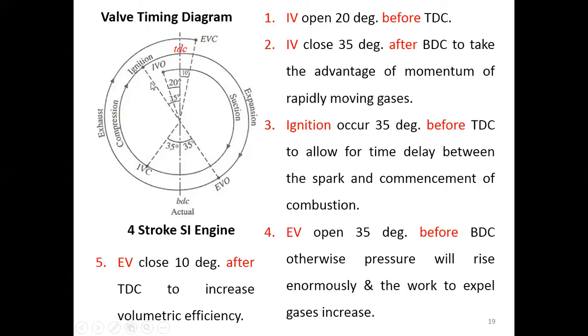Okay. Start from the inlet valve here. The inlet valve opens here. From the valve timing diagram, we can see that the inlet valve opens 20 degrees before the top dead center. This is the top dead center here, right? And then it keeps opening, so the suction or the intake happens until it's closed here, right? From the valve timing diagram, we can see that the inlet valve closes at 35 degrees after the bottom dead center.